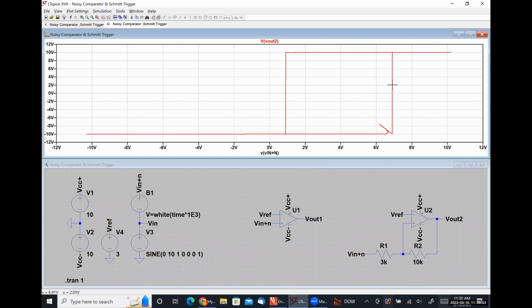In fact, in one of your design problems, I asked you to use a Schmitt trigger to make an analog to digital converter, where instead of arbitrarily saying when it's above this level it's a digital high, and when it's below this level it's a digital low, if the input voltage is 3, it should transition to high, and if the input voltage drops to 2, it should transition to low, and then you have that latching in between, so that it's not a simple binary decision.